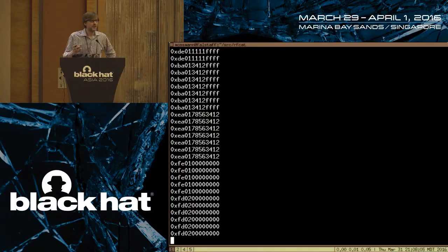seem to be a lock or unlock code, or like an action code, followed by a checksum. And this is a very common sort of checksum. Do you notice the lock code is a 1 and the unlock code is a 2, so that's kind of easy. And then the checksum, when I changed the action code by just a little bit, the checksum changed by just a little bit, which is a good indication that this is a simple checksum algorithm. It's not a more complicated algorithm like a CRC, but it's only an 8-bit checksum.